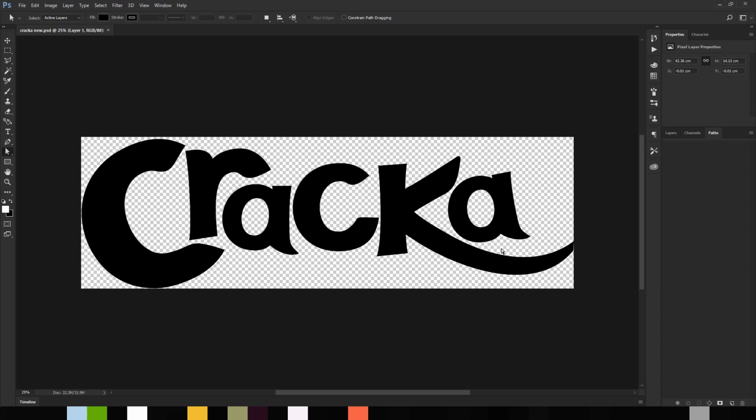It is a bitmap. Before Photoshop converts a raster image to a 3D object, it automatically creates a work path. It creates a path around that image in order to be able to extrude. And so it is actually extruding from the path, not the raster image itself. For the extrusion to look smooth, the curves on the path need to be very smooth. They need to curve along the edges of our object, of the layer that we are working with.